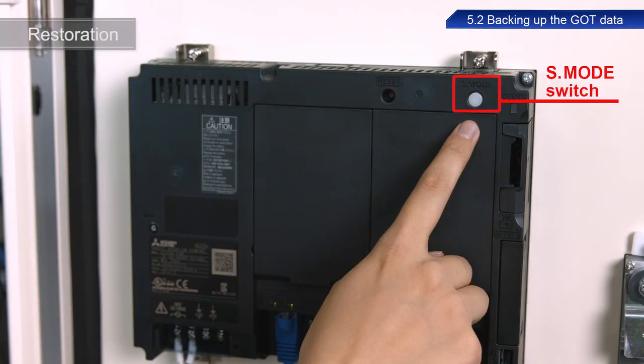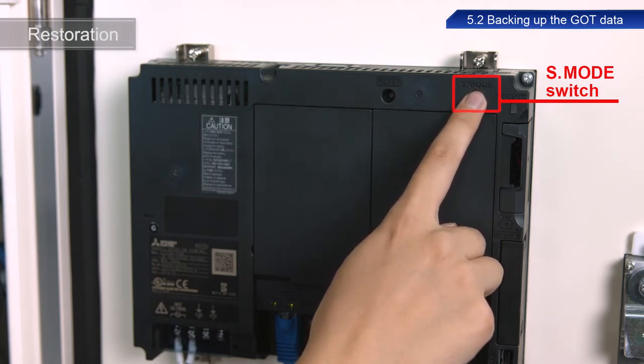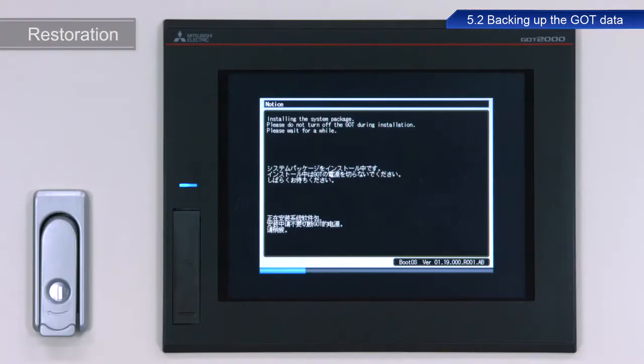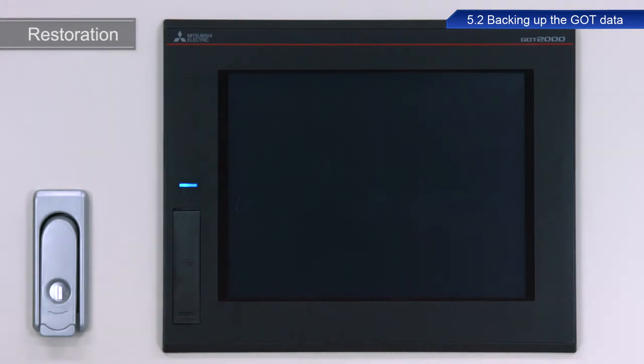Now we will restore the data to the newly installed GOT. Turn on the power to the GOT while pressing the S-mode switch at the rear of the GOT. The installation process now starts. Do not remove the SD card or turn off power to the GOT while Install Now is displayed. Once the Installation has been completed message appears on screen, touch the screen to restart the GOT.